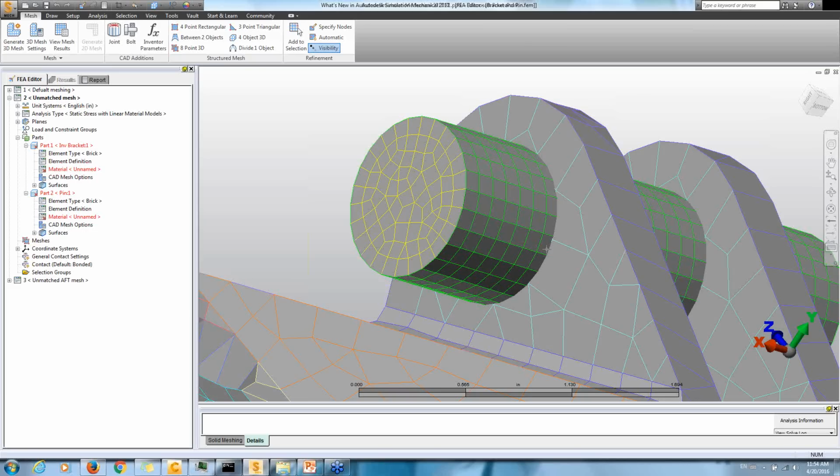And if you wanted the surfaces to be bonded, you can of course use the smart bonding for simulation mechanical. For Nastran, it's a default. Yeah, it's unnecessary to have. You don't need that extra step to say, hey, use smart bonding.